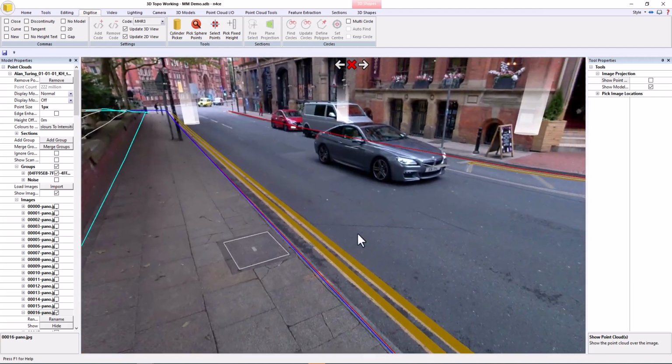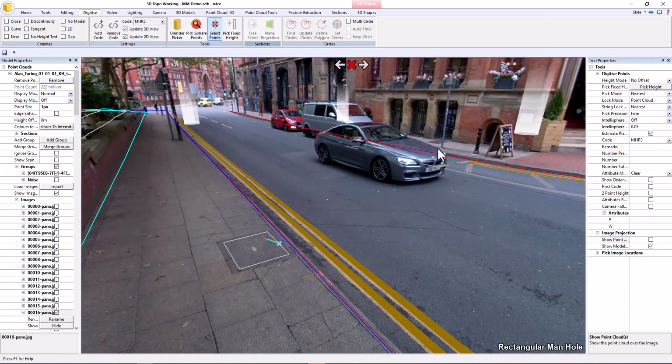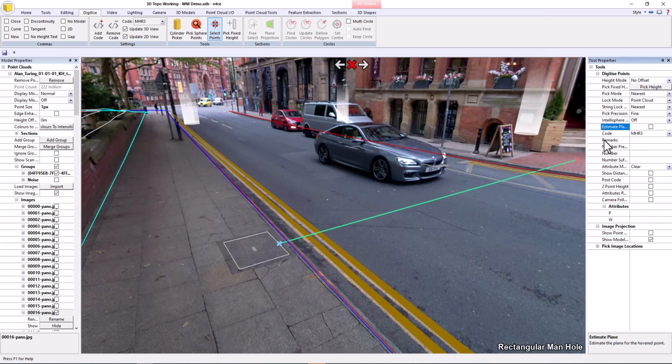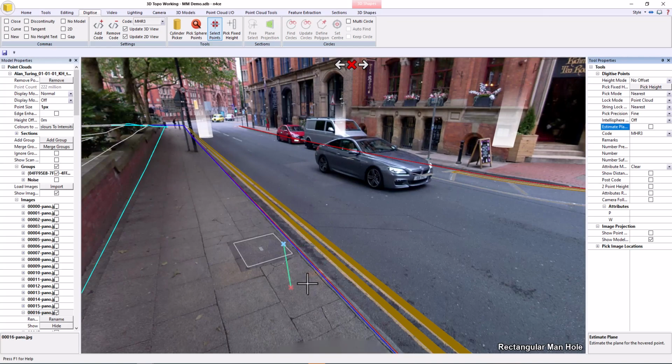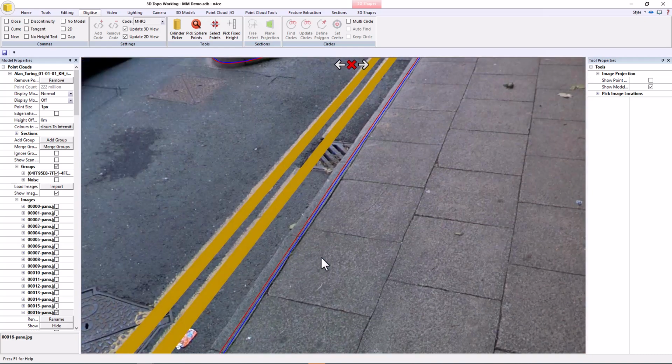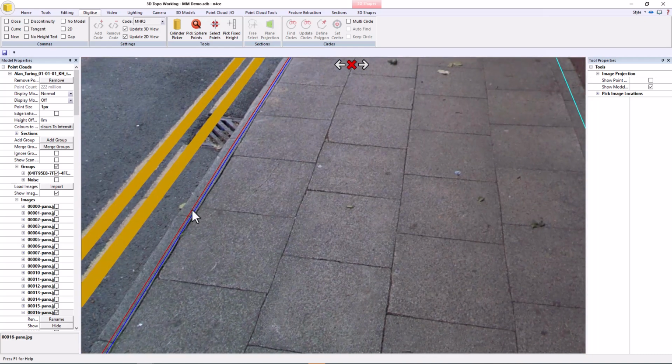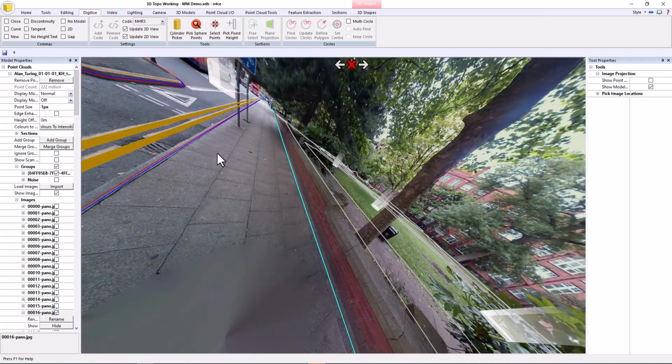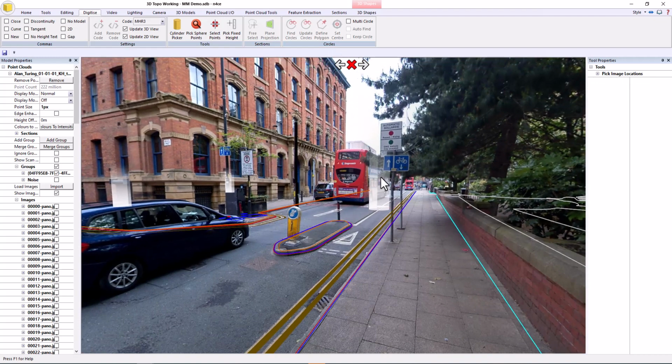Okay, so that's when digitizing. Now you have the estimating plane tool as well as the normal pick tools now to help you click exactly where you want. You don't have to just rely on a point being there. Otherwise a lot of these were picked up using both 2D and 3D tools. So I digitized the curb and then I just paralleled it up in the 2D view, locking to the highest levels in that location, and same with the yellow line, just drew one and then paralleled it over the appropriate distance.